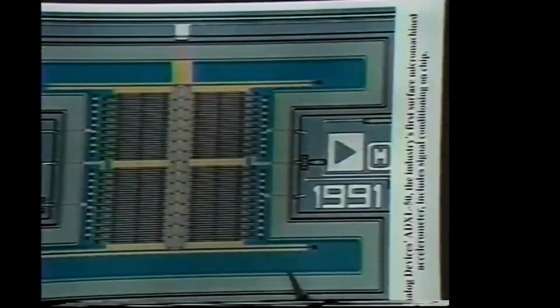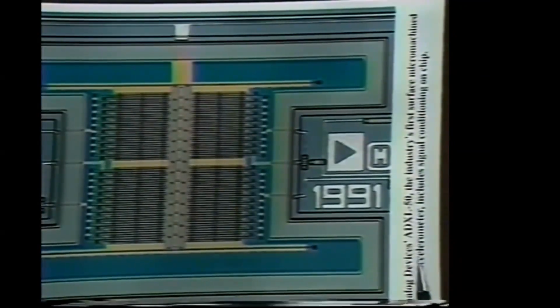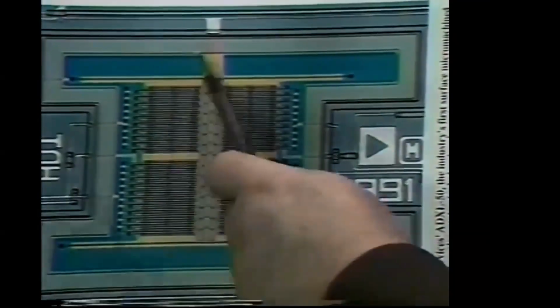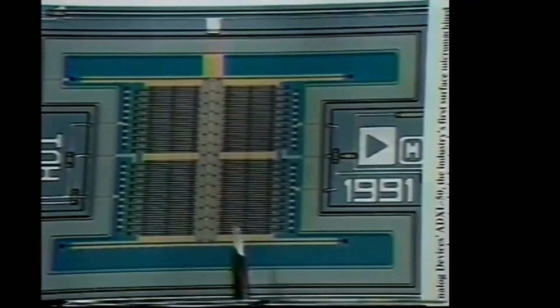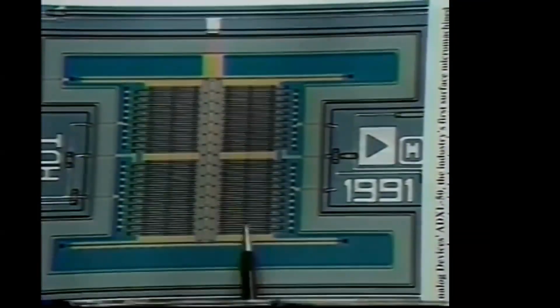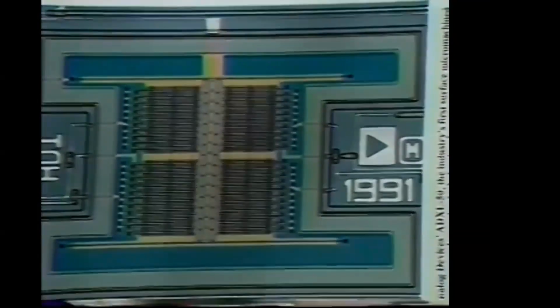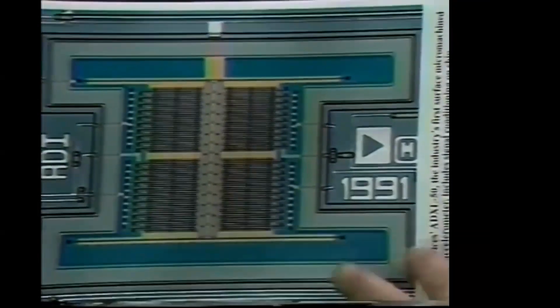These thin films are dielectrics on the order of a half wavelength of light, and they show that the sensor in actuality is 42 differential capacitance cells. Half of the proof mass is actually in the fingers that stick out, and half the proof mass in the center member. And again, this resides about 1.5 microns above the surface of the silicon.